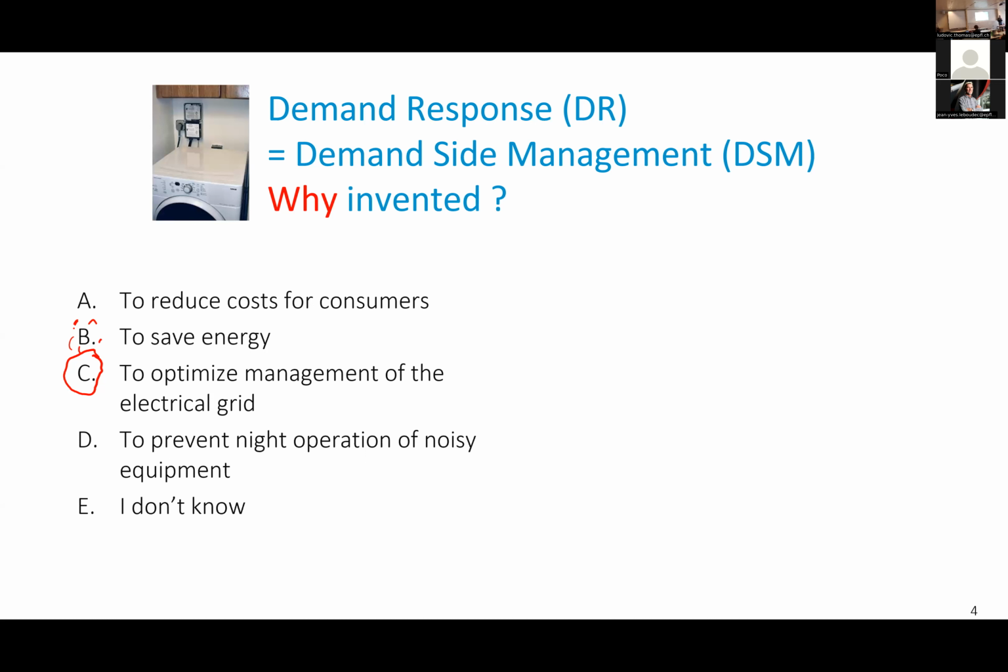So what it did is, at 5 o'clock, it started raising the temperature of the house by 2 degrees more, and then it stopped heating at 6 o'clock, and then the temperature dropped, but since it was a bit higher, it was still comfortable. In fact, what this has done was to store electrical energy in the form of heat in the house at 5 o'clock in the morning. That heat will, of course, be lost and dissipate, but would be used to heat the house and keep the house warm at the time when electricity is expensive.